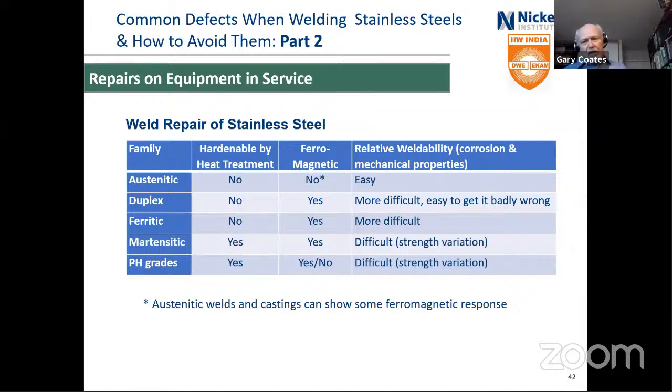The duplex alloys are more difficult because they do want cleanliness. You do have to be careful about both minimum and maximum heat inputs on them. It's easy to get it badly wrong, and by badly wrong, the weld may look great, but it may corrode very quickly in service.